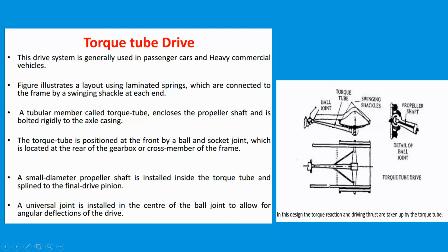A torque tube system is a power transmission and braking technology that involves a stationary housing around the drive shaft, often used in automobiles with a front engine and rear drive and rear brakes. The torque tube consists of a large diameter stationary housing between the transmission and rear end that fully encloses a rotating tubular steel or small diameter solid drive shaft that transmits the power of the engine to the regular or limited slip differential.